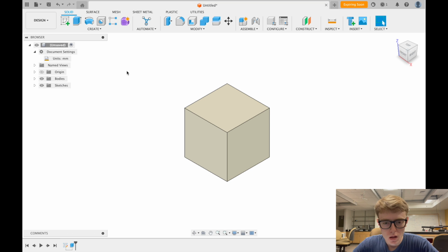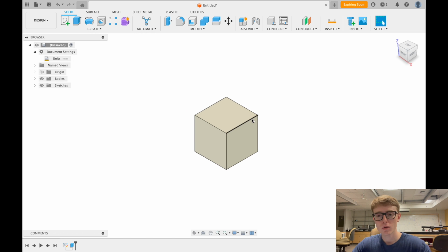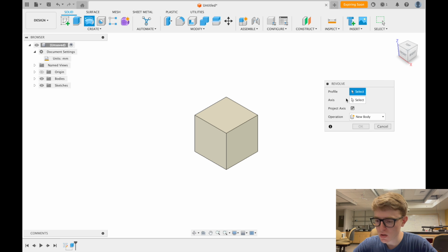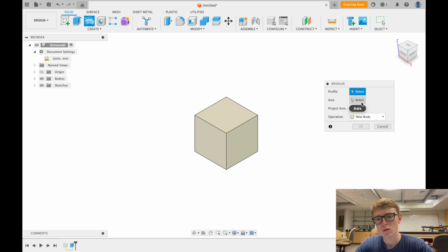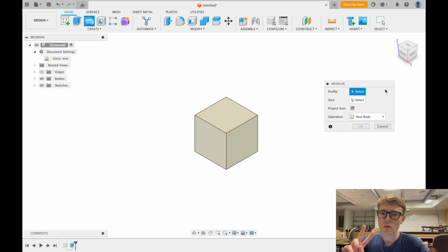Okay, cool. So now what I'm gonna do is I'm gonna show you guys revolve. So once again, we're gonna go back through the same sort of steps. We're gonna have a sketch, and then we're gonna come out of that sketch and we're gonna revolve it. I'm using this create tab right here, revolve. Okay, but first we need to know, well, what are the requirements for revolve? So let's just click on revolve. I could tell you what it is, but I can also show you. So what revolve requires is you need a profile. So that's the thing that is being revolved. And then you need an axis. So that's the thing that the profile revolves about.